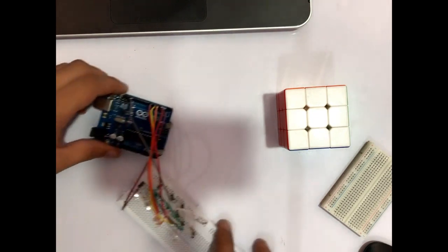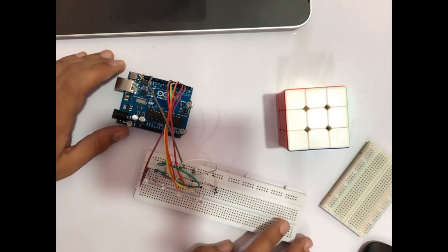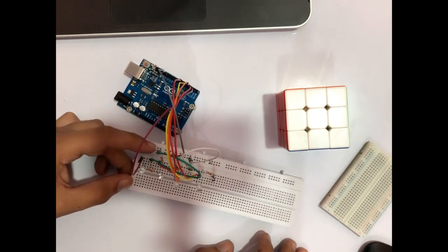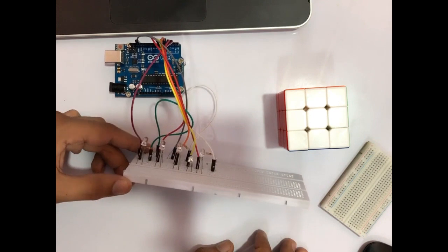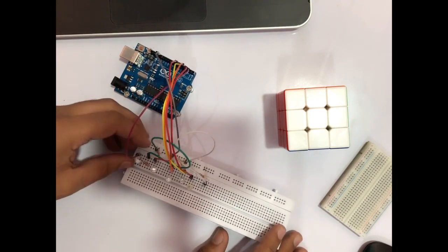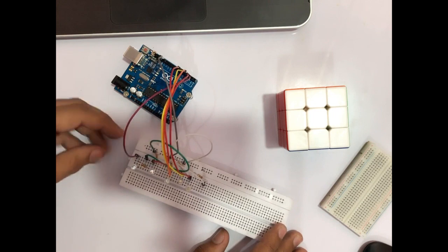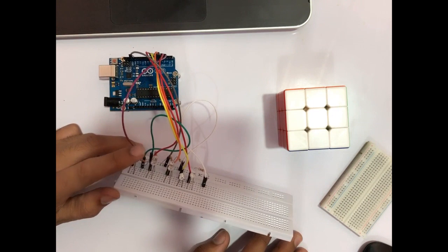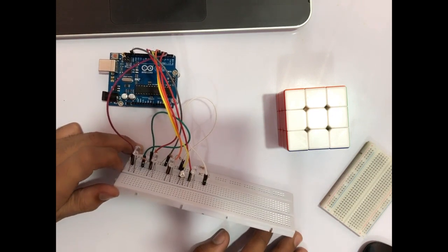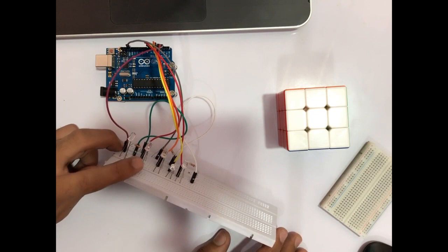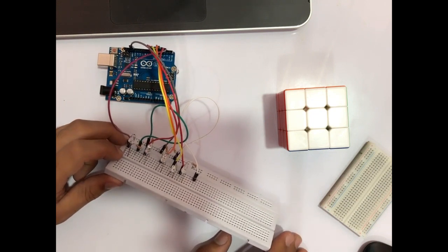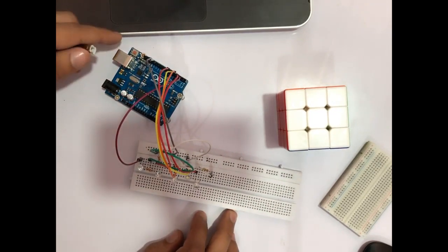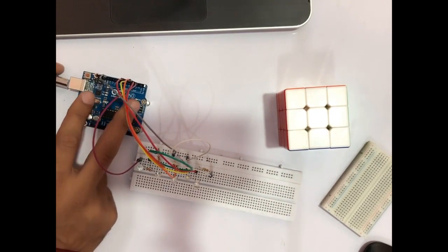So here we are on the board, and here we have connected 5 different LEDs to the Arduino, and as you can see here, they are commonly grounded, and we have also uploaded the code. So now let me power up the Arduino and check whether all of these will glow or not. As by the concept of loop, we have defined a single array containing all these 5 LED numbers, and they will glow by just using a single variable.